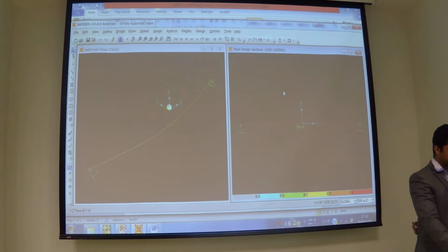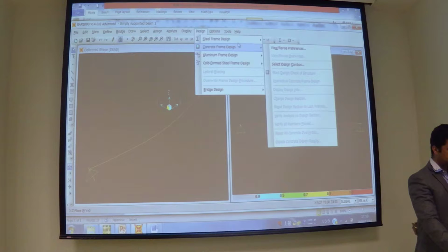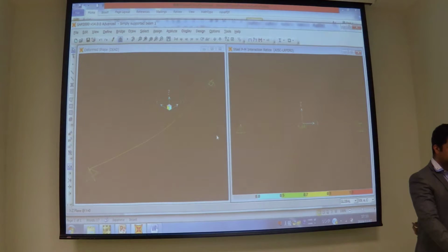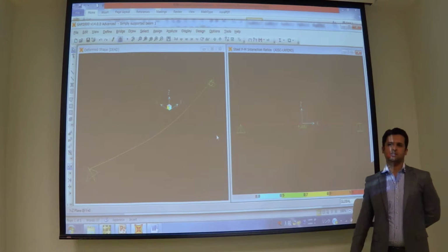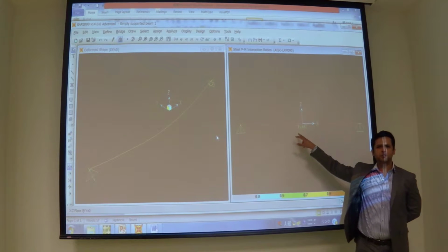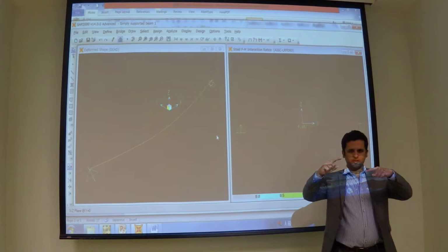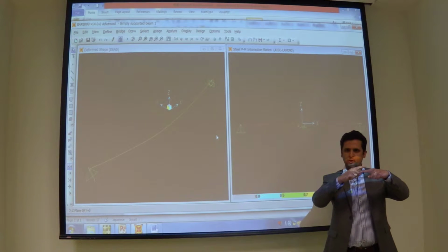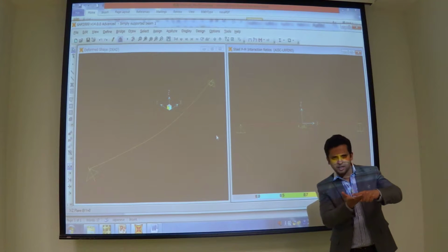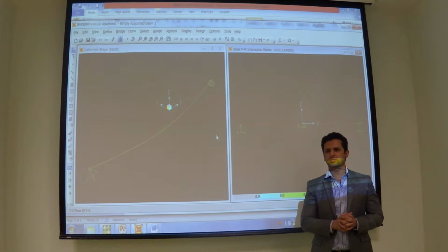Start design and check of structure. Beam 1. Design steel and display design information. Okay, it's badly failing. This ratio is 4.62. What is this ratio? This ratio is the required bending moment, how much is that? 75, divided by the capacity of beam.